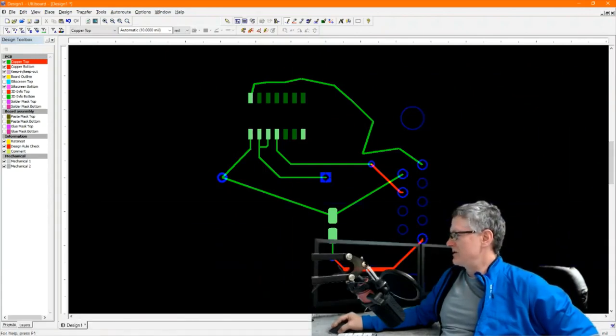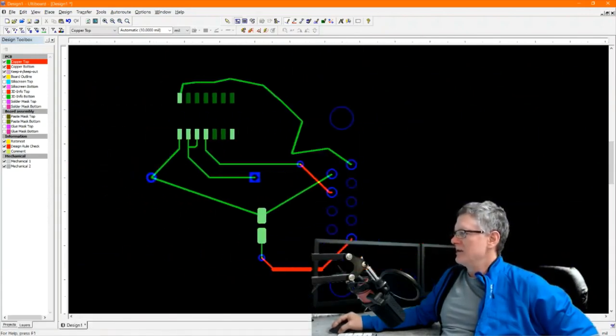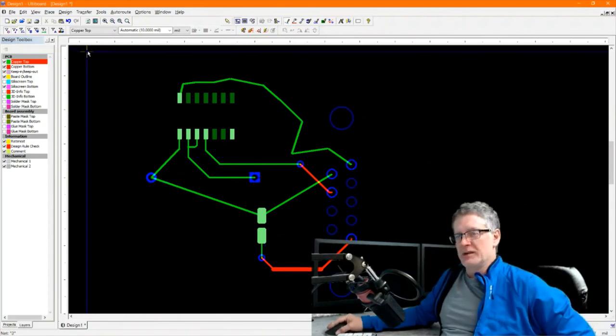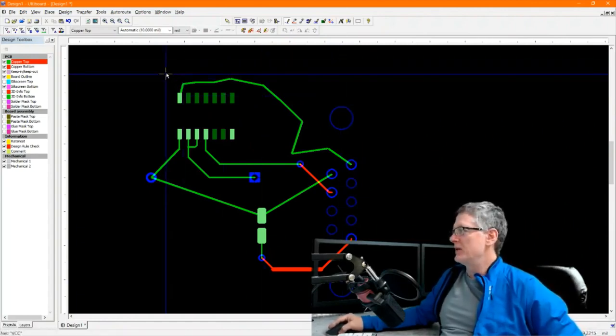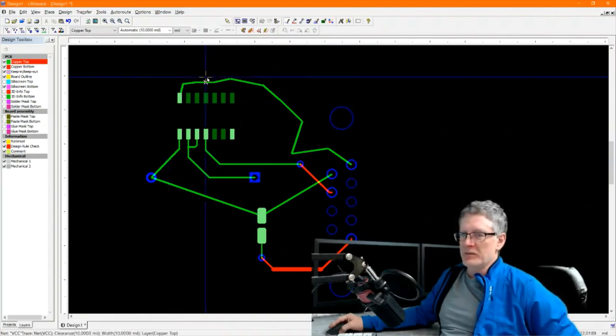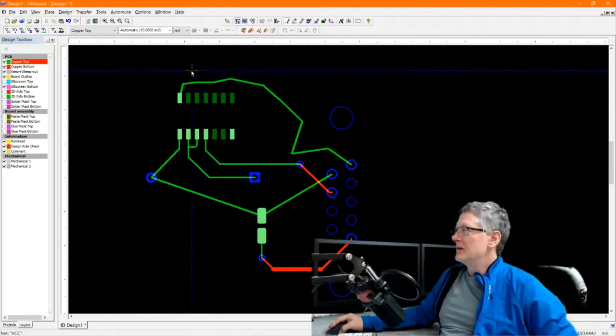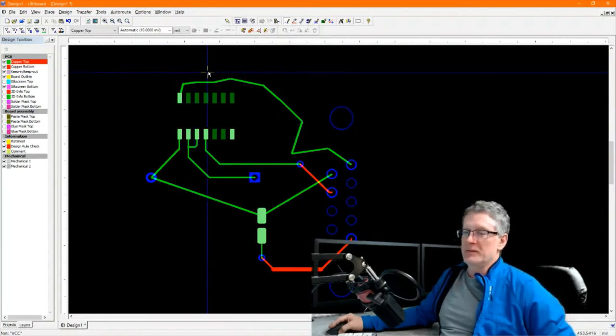There's kind of a short introduction to layout. You come in, you place your parts, go for minimum crossovers and short distance, doing a trade-off between the 2. You start routing traces between points, one on the top side, one on the bottom side. So I think I'm going to end this video here. And in the next one, I'm going to show you a couple more features that you will use when you get into it.